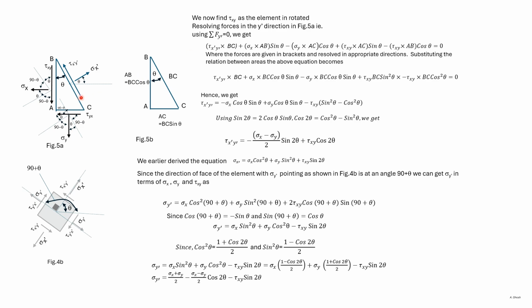Here we'll resolve the forces along the y dash axis to obtain tau x dash y dash. So we use the equation summation F y dash is equal to 0.